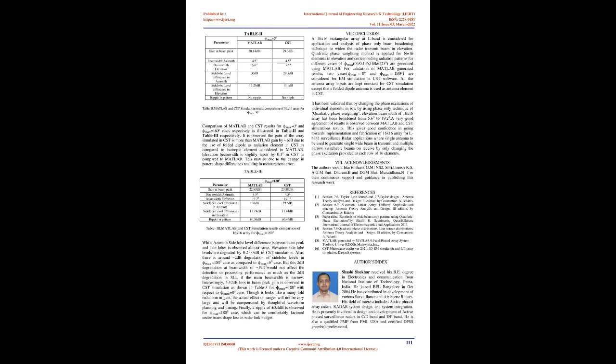6. Validation of MATLAB results with CST simulation results. For validation of the proposed method, simulation has been carried out in CST for the 16x16 array as configured in MATLAB, for two cases, φmax equals 0° and φmax equals 180°. Design inputs for CST simulation are the same as given for MATLAB, including Taylor weights and phase weights, except a microstrip-based folded dipole, gain of 4.8 dB, BWAZ x BWEL equals 75° x 125°, is used as antenna element for simulation purpose.